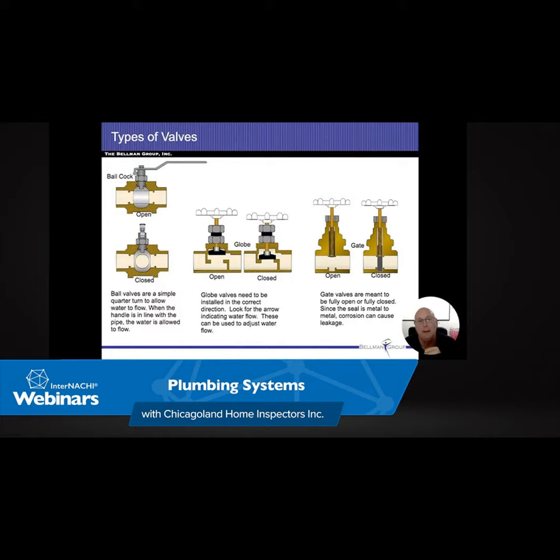This is just the basement of a residential building. You see the pipes are white and plastic. Those are PVC. They're using them for the hot side, and that's where our problem comes in. Fine for the cold, not so fine for the hot. All right.